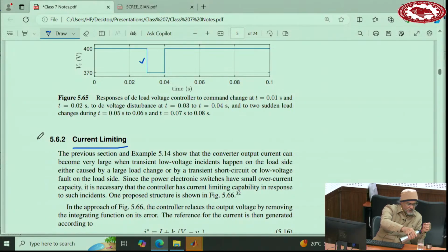That's a very good question. However, my answer is, when you say this converter is supposed to operate at the rated 1 kilowatt, that's the rated value. It can go from 0 to 1 kilowatt, and even maybe slightly above 1 kilowatt, depending how much room you have given to your switches and everything, because switches really determine the rating, right? So in this kind of application, this is the common practice. You design it for the rated value, because we don't have any other really. If we don't do that, what should we do? We should start from somewhere.